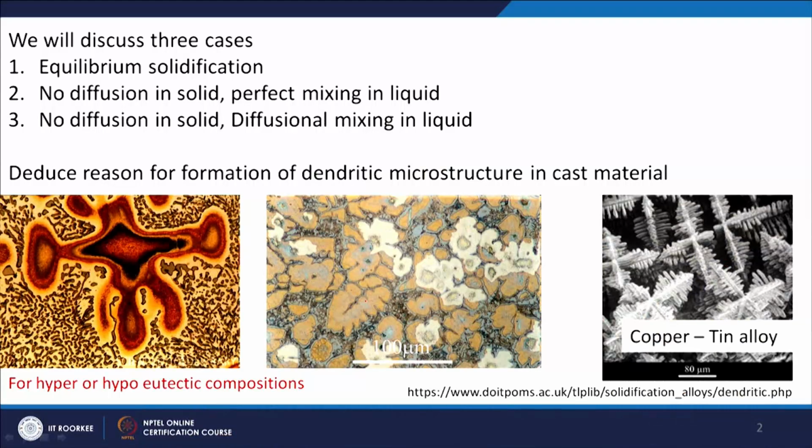You can see that there is a large variation in the microstructure, and of course there will be compositional variation also. So you have all these dendrites, which are pro-eutectic phases, and between two dendrites you have an interdendritic region which is a eutectic phase. All these things we have to take care of in the subsequent processing.